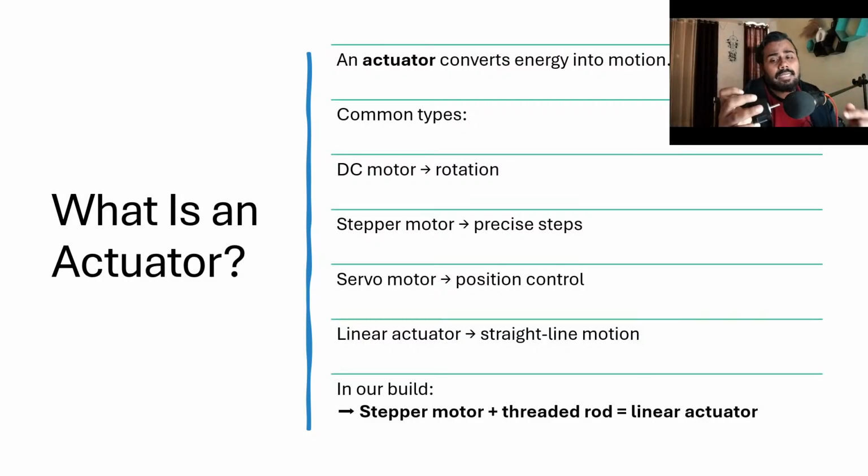By using this motor we can have 200 steps of control over its movements, right? These electromagnets get activated via these 4 colored wires. They create small electromagnets when the current pulse passes through, and that pulse can control the motion in whatever way we want. This motor